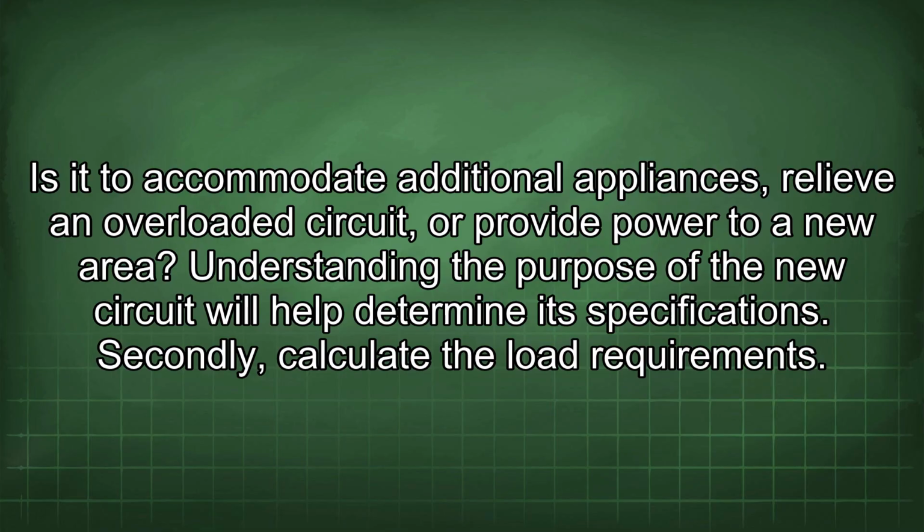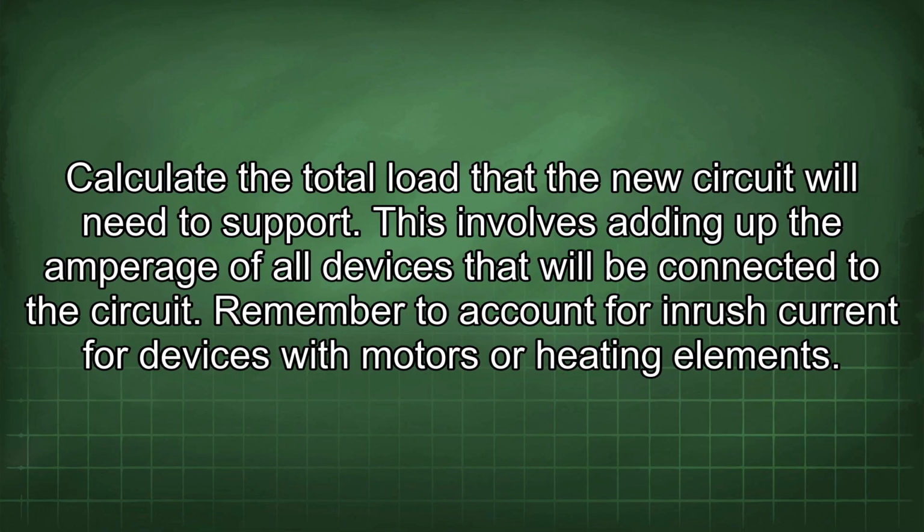Secondly, calculate the load requirements. Calculate the total load that the new circuit will need to support. This involves adding up the amperage of all devices that will be connected to the circuit. Remember to account for inrush current for devices with motors or heating elements.